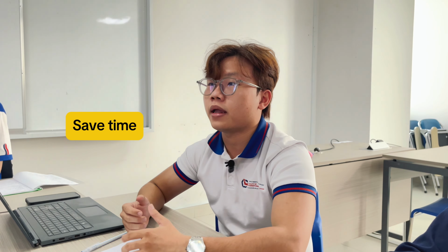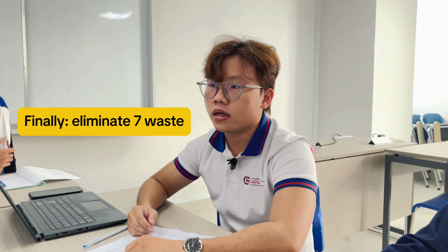Great! To sum it up, remember the main goal of JIT is to balance the system and achieve a steady and continuous product flow, reduce inventory, save time, and optimize manpower. To achieve this, we need to firstly eliminate disruption, meaning that we have to deal with equipment breakdowns, changes in scheduling, and supply delays. The second one is to increase flexibility, meaning the system should easily adapt to changes to optimize production. And finally, eliminate waste, meaning reducing overproduction, waiting, transportation, excess inventory, excess materials, defects, and unnecessary motion.